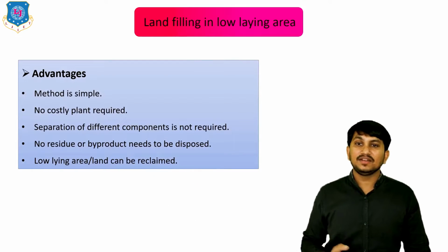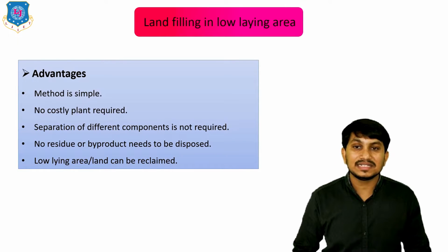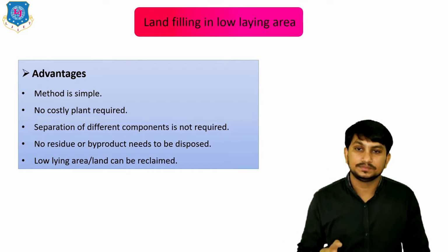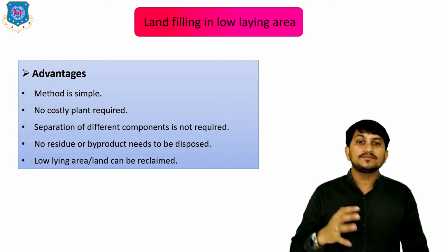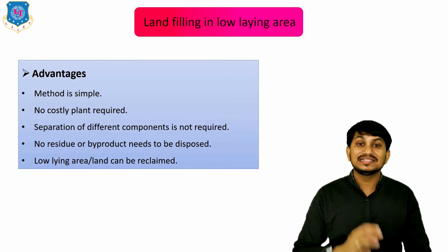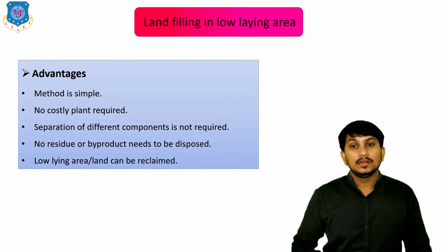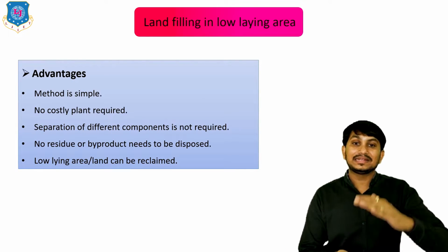The advantages of the landfilling method: the first and main advantage is that the method is very simple. No costly plant is required. Separation of different components is not required. No residue or byproduct needs to be disposed. Low-lying areas of land can be reclaimed or increased.